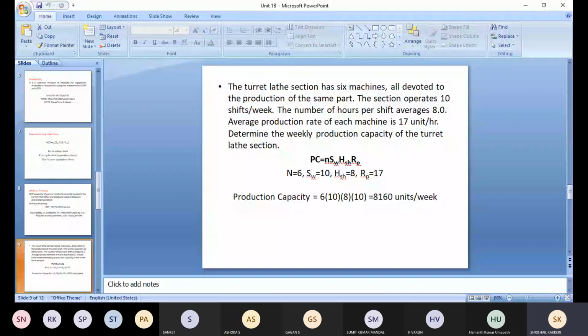And integration of operations. Integration of operations is integrating two machines. For example, once a part is completed in one work center or machine, it has to be carried to the next machine. To do that, a worker is required. He has to orient the part and take it to the next machine, so the non-operation time will be increased. To avoid this, we can have a conveyor, some kind of automated device which will convey the part from one machine to the other machine.